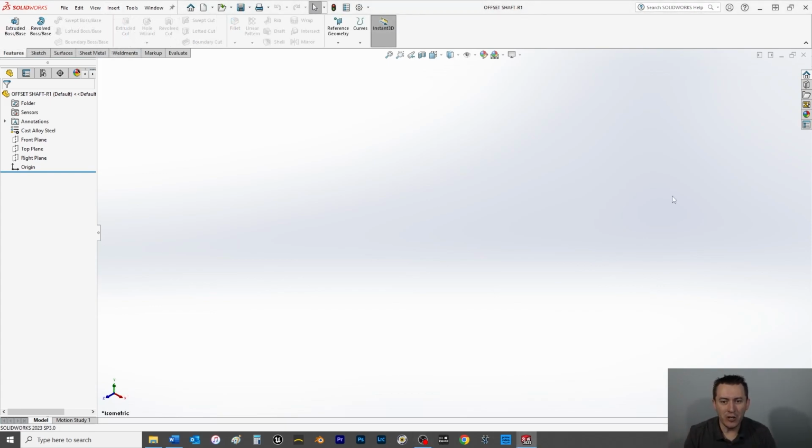Alright, so we're going to start a new part file as usual. You can reference the first video in this playlist to see how we use the ANSI cast alloy steel part document template to get to this point. And of course, once you create a new part, I always recommend saving first, and in this case you're going to save it as the offset shaft.